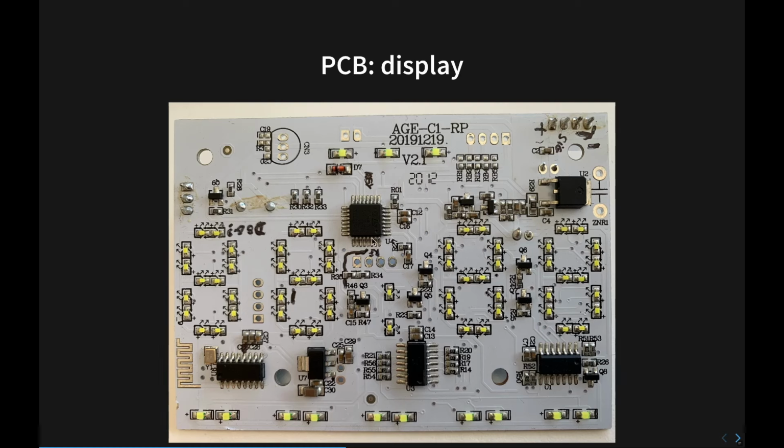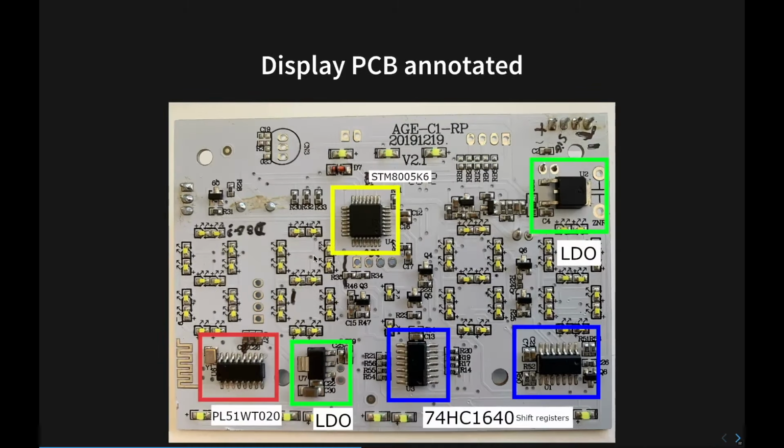Sometimes you will be lucky because those pins have pre-selected functions, so it's easy to infer the function, but it's even easier to have a little bit more knowledge of how the actual board works. Here I made a few drawings of which components are which. Here's the STM8 part, whose firmware can be downloaded through these pin headers on the board.